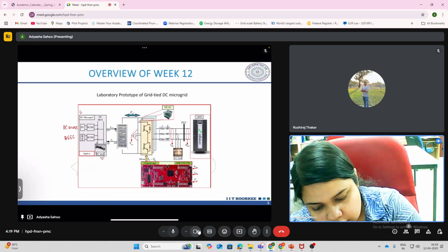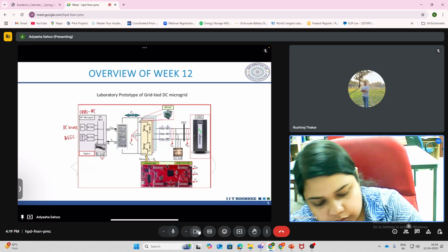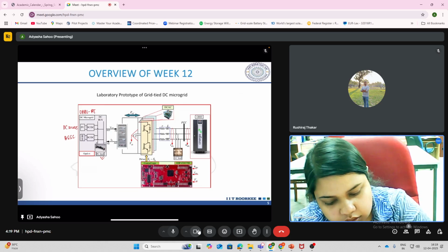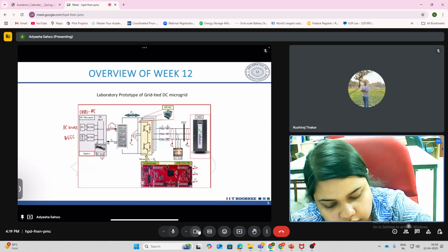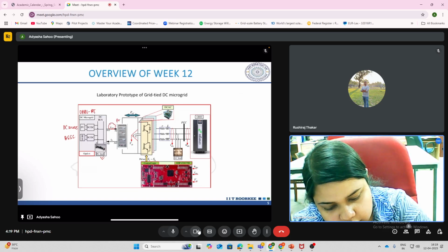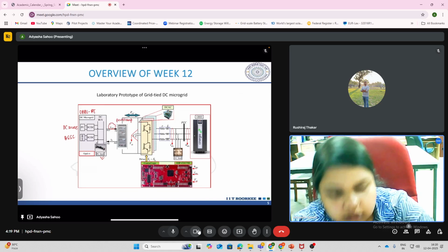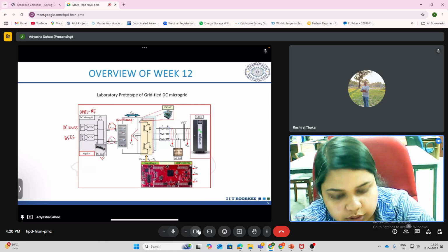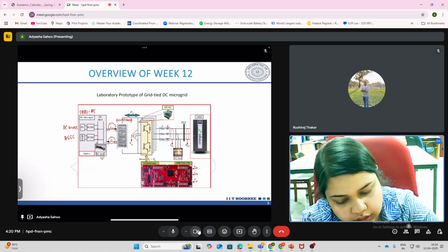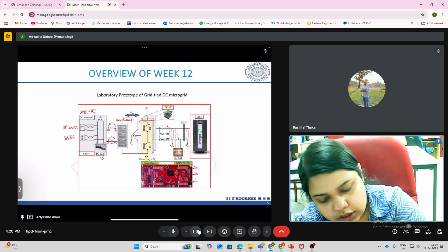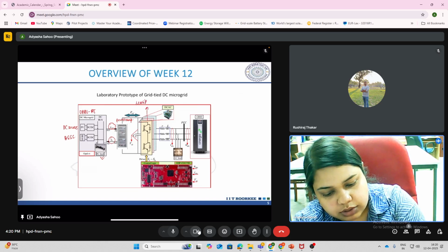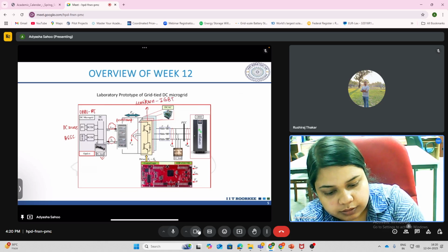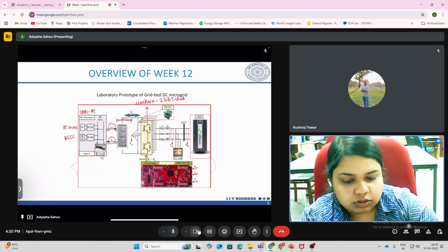Now, this DC microgrid is realized using the OpenRT platform, and this is giving the required voltage signal. This V out you can see here, and this is the power amplifier. By sensing the voltage here, it is generating the current signal back to the DC microgrid, completing the loop here. Then next you have this inverter, which is realized using that Semikron IGBT stack that we have been discussing from the past few lectures. So the inverter is realized using this device here.